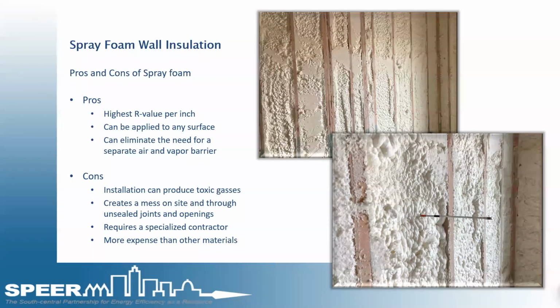In the lower right-hand corner, you see this was just a simple meat skewer that had tape on it. What we did was stick it in the foam. If the 3.5-inch cavity was anywhere within that orange tape, it was adequate for insulation install. If a 5.5-inch cavity or roof rafter actually hit anywhere within that black, then it actually met our compliance. So an overall average of the right insulation was done. So we moved on from there.